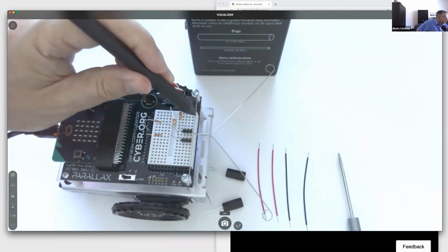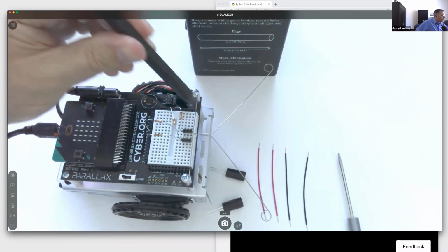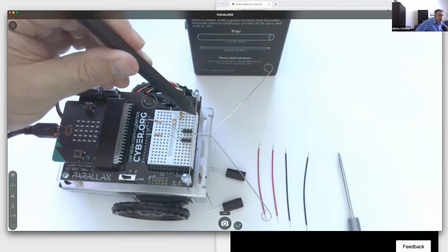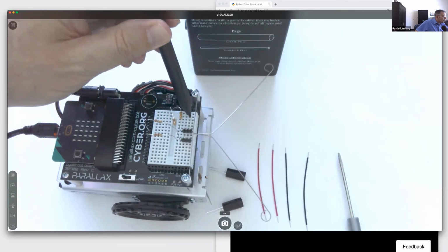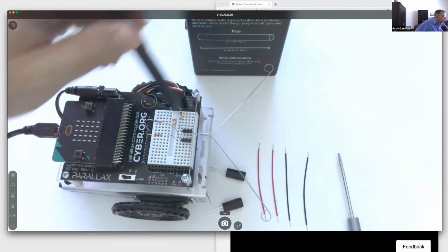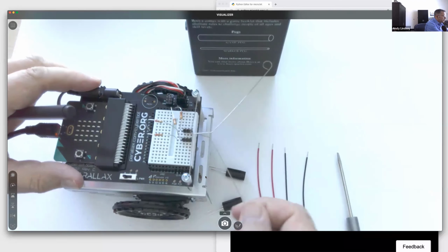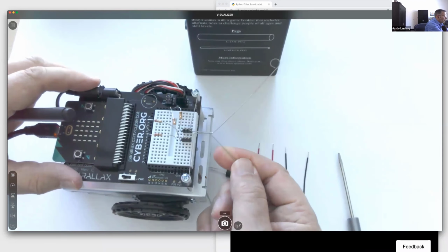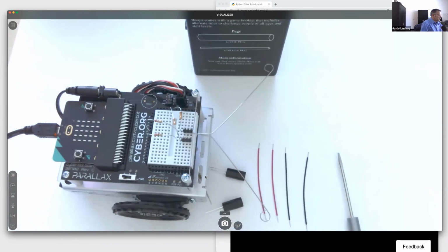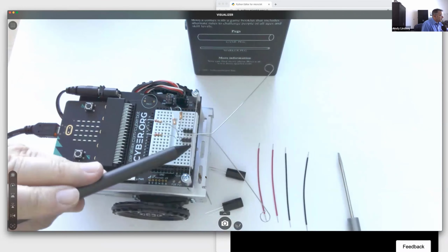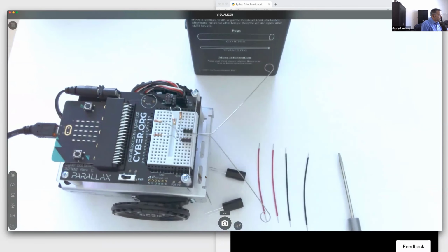So we'll leave that for if you want to try it with your students. Just remember, you'll want to put electrical tape around this part of the whisker because we'll have our infrared parts built right here and right here. And if the whisker happens to pass too far, it might end up pressing up against those electrical parts and could even damage them. So again, electrical tape around the whisker here and there if you decide to do this.